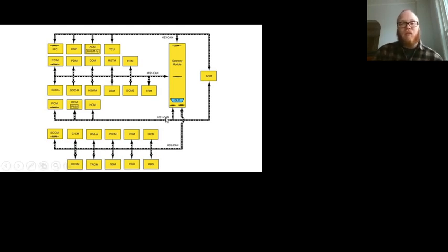So long story short, what's happened is there's this gateway module that now acts as a gatekeeper for the scan tool. It can translate information from the medium speed CAN or high speed CAN 3 to the data link connector, so that we can pick up the information and actually pull codes and look at live data and try to diagnose what might be going wrong with a radio or an auto opening tailgate. Who knows, right?